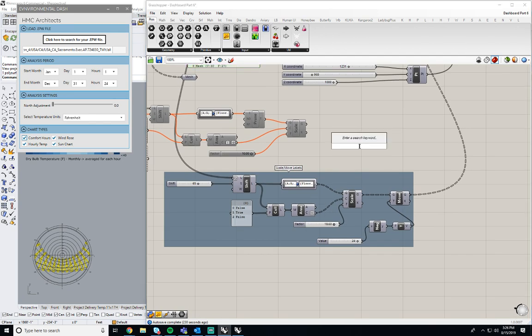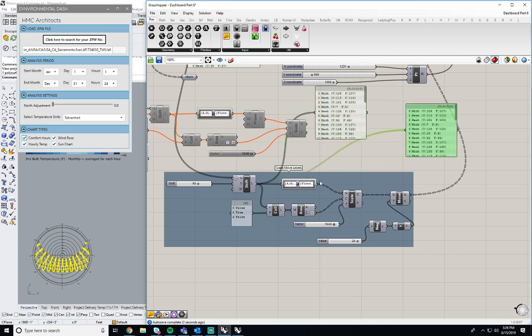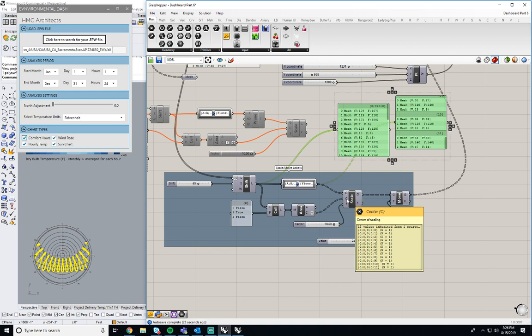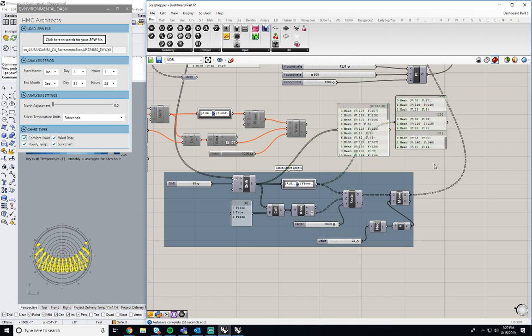I am transforming the list from a single list into a tree structure with lists of 3, since I know that all the months are abbreviated with 3 letters, which then allows me to scale all 3 mesh objects with one center point, instead of having to scale each letter based on its own center point, which would essentially be messy if you scaled those letters too large, and they would overlap.